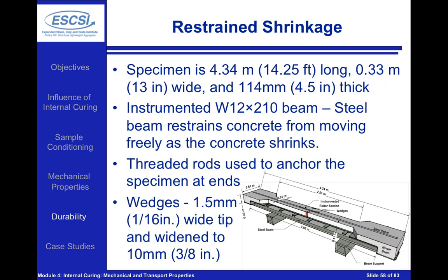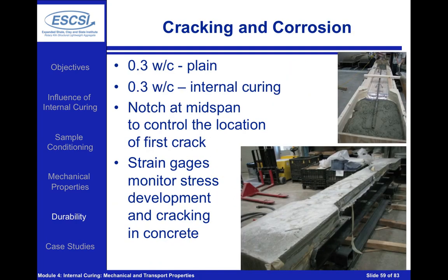So here you can see some of the details. I won't spend a lot of time on the details of this particular experiment, but we've got a section that's about 15 feet long, and in the center we have an instrumented rebar. And that rebar is being instrumented in the center. We're going to look at a 0.3 plain concrete, a 0.3 internally cured concrete, and we're going to make sure that the crack is going to occur in the center by using some small notches to make sure that that's going to be a weak plane in the system.